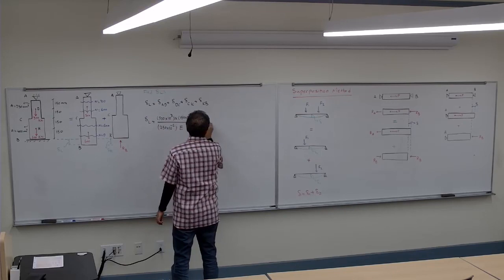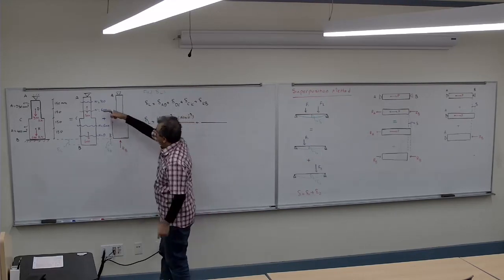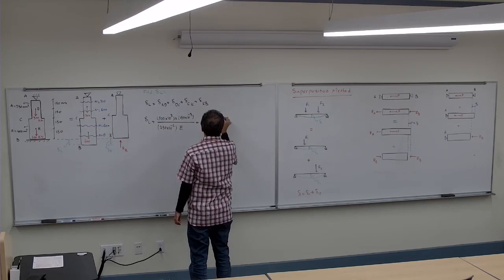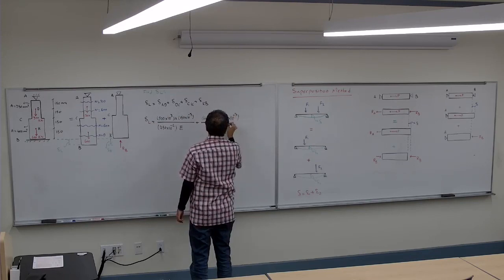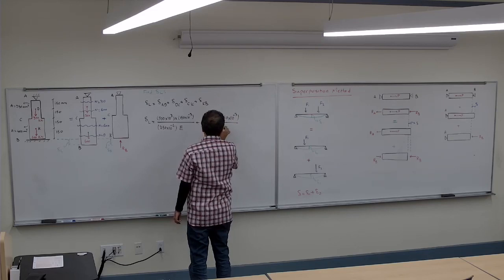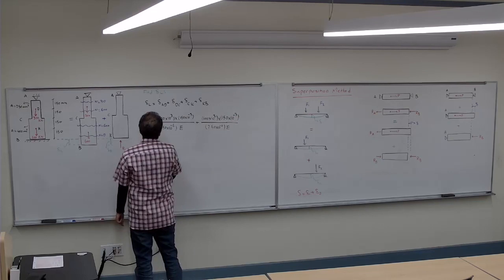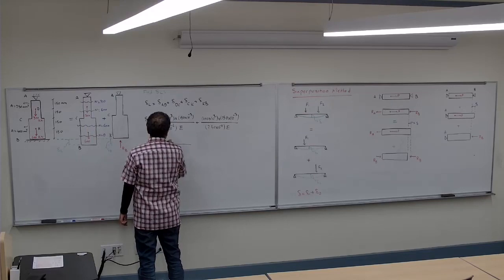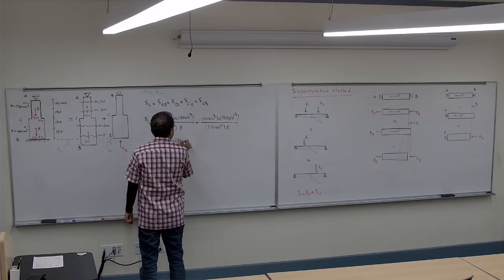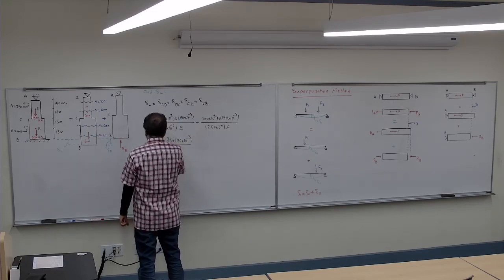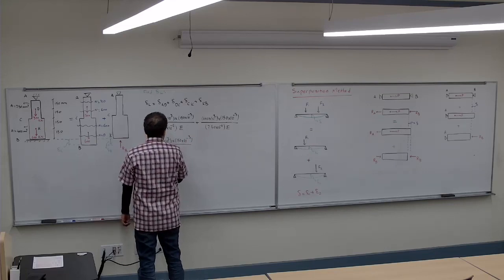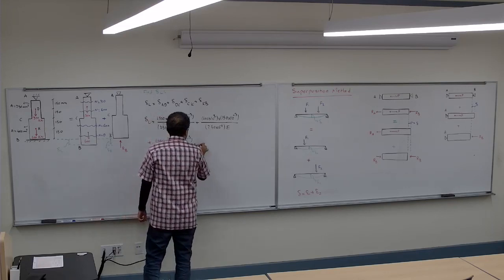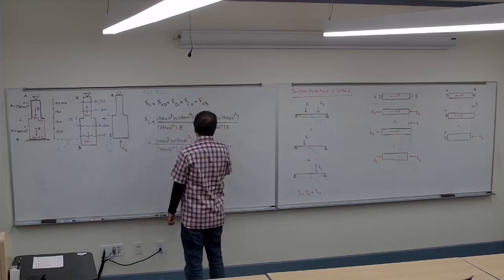So it's going to be plus, from the D to C, 600 times 10 to the 3 times 150 times 10 to the negative 3 divided by 250 times 10 to the negative 6 E, plus the CK, again it's going to be 600 times 150 divided by 400 E, plus 0.